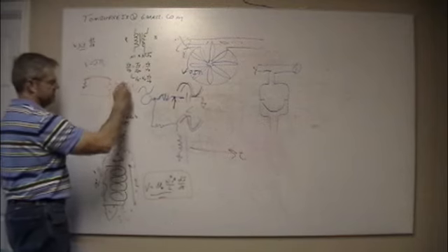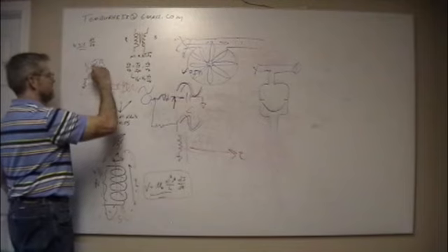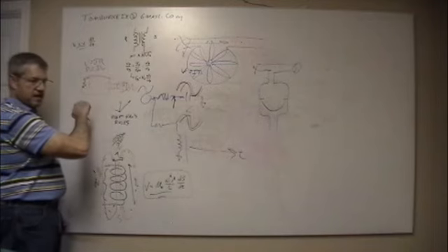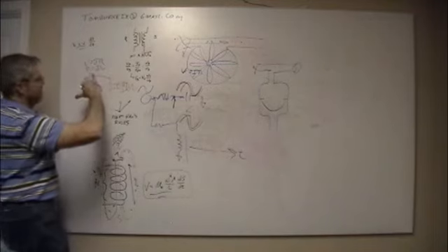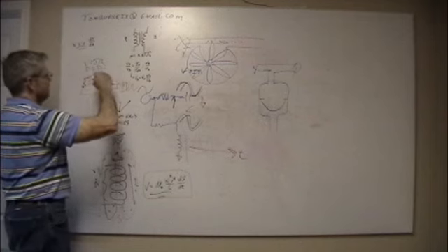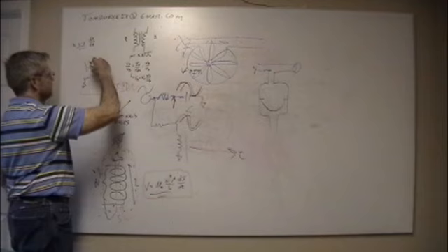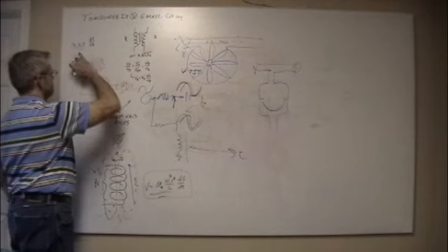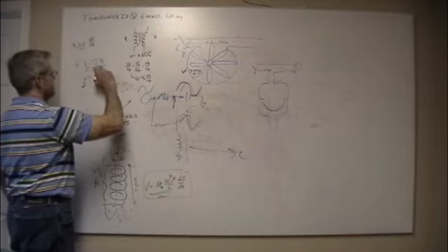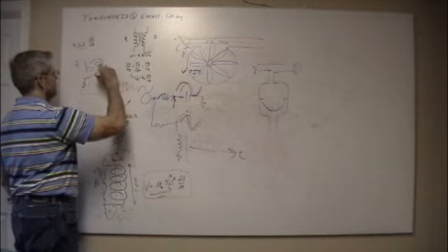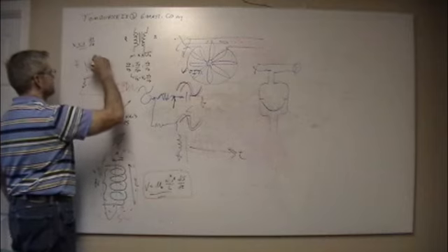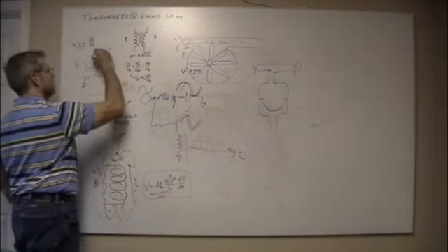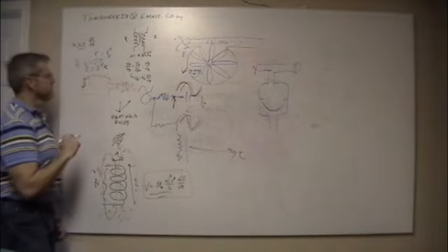And so I can figure out the power being dropped, P equals IV. There's my two major Ohm's laws. I can say there's this much current in this line, but now if I'm off peak and my voltage is down, I equals V over R, or let's do it, P equals IV, I squared R, or P equals V squared over R, right? Those are a couple of different equations that we can pull out of that.